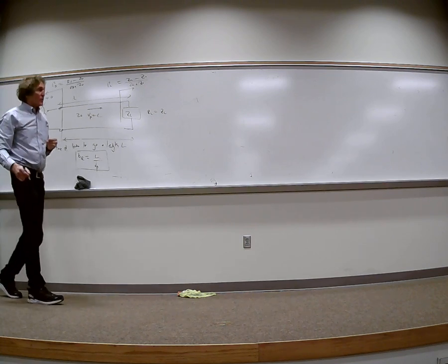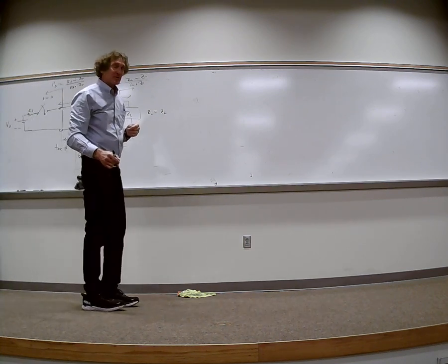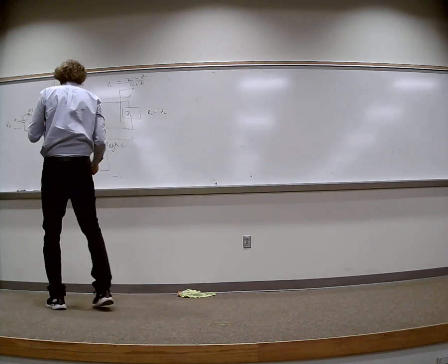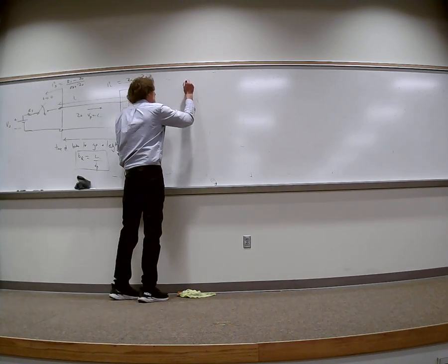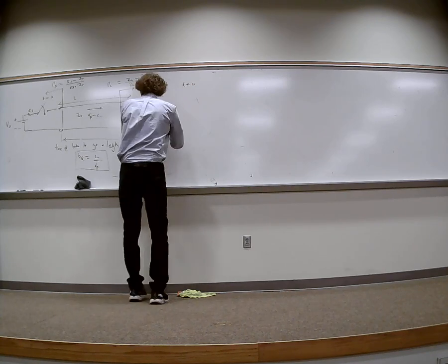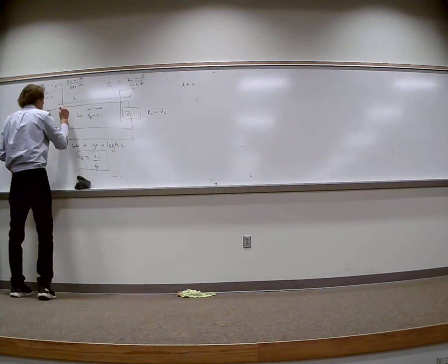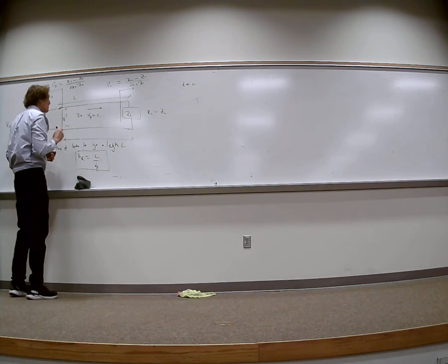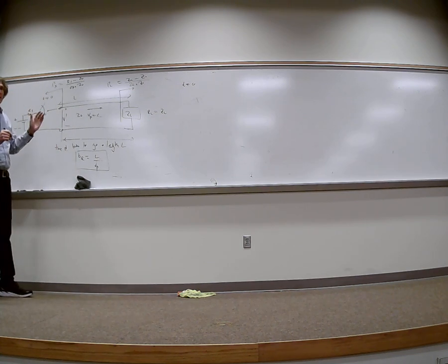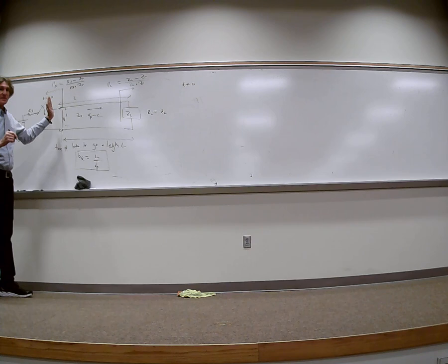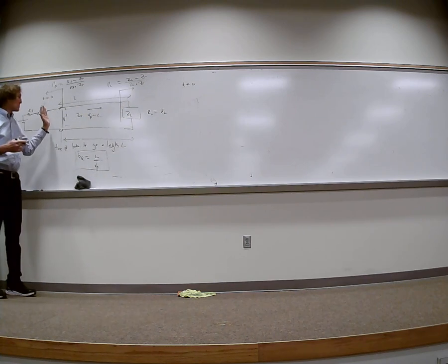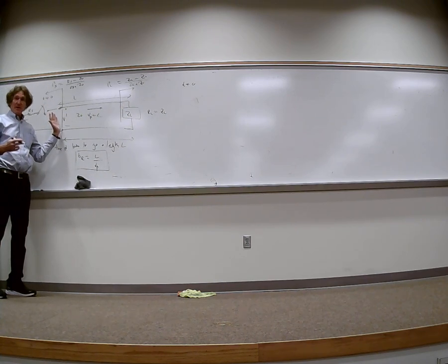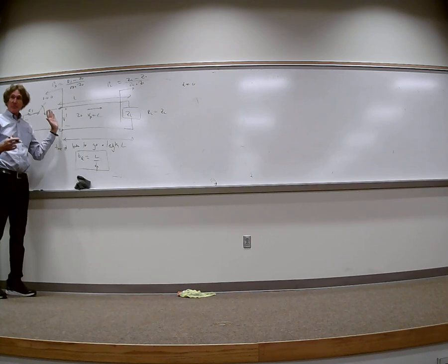Now, the way we do this is kind of interesting. We first say, just as that switch closes at t equals 0, what we do is find the voltage right here, and I'm calling that V prime, that's going to be actually introduced to this line and will propagate at the speed of light. Remember, this line, when that switch closes, doesn't know what's down here. The only thing it knows is the impedance it sees right here. Y'all follow me? Everybody on this one?